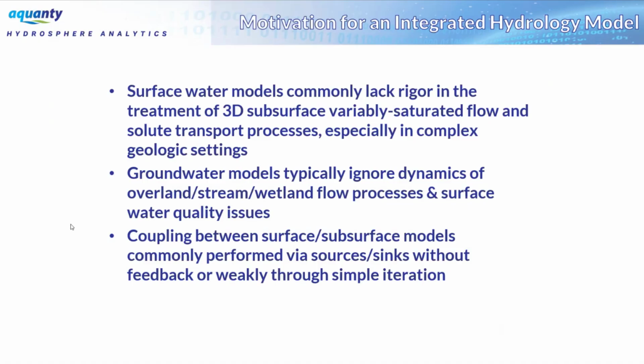So this is what HydroGeoSphere is really all about. Now, why would we even want to take an integrated approach to hydrology? Well, surface water models and groundwater models, as I mentioned before, have to represent the opposite side of the hydrologic coin as boundary conditions, right? So a surface water model will have a prescribed base flow value typically.